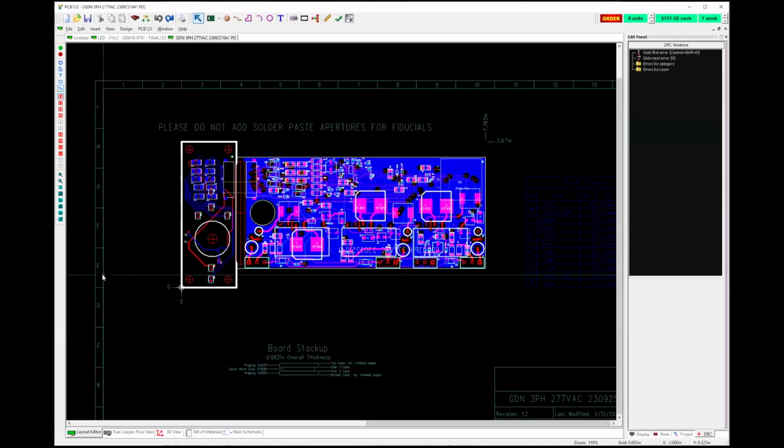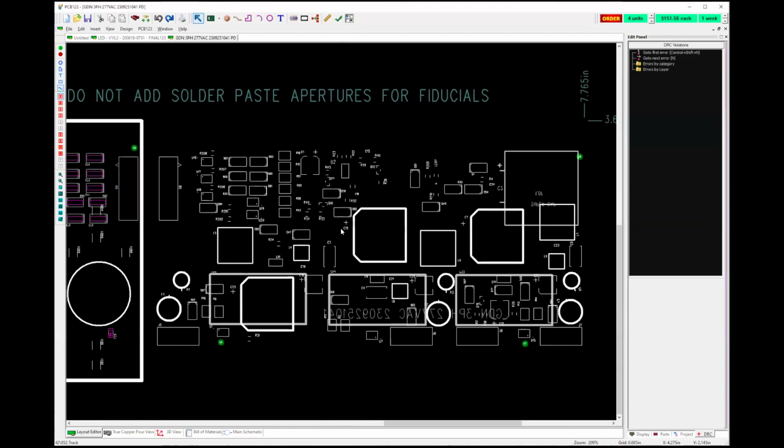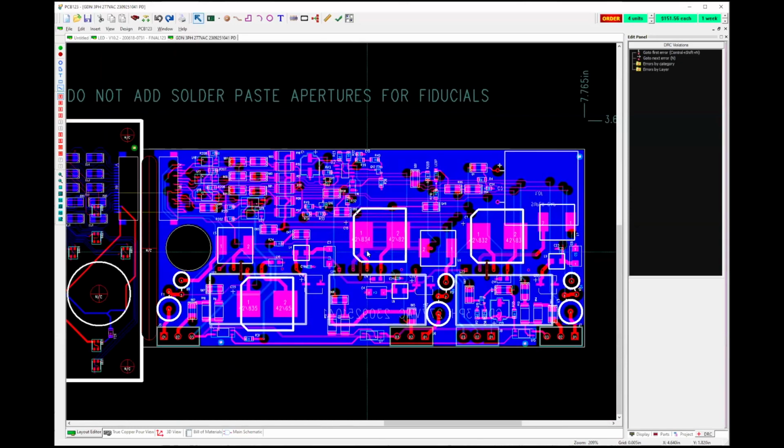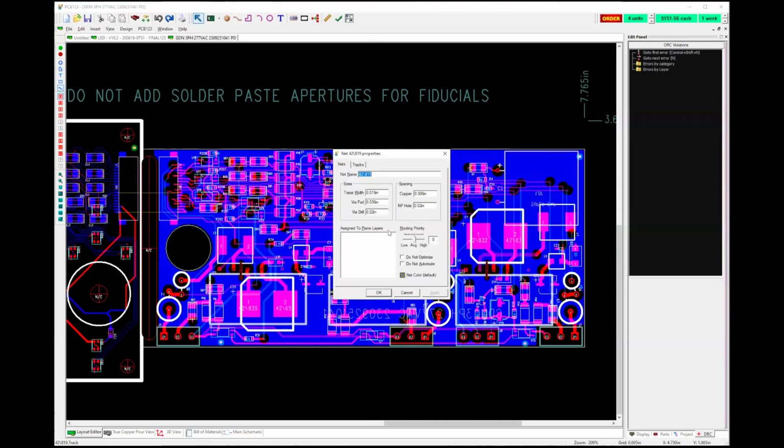Now, hey Bob, yes, quick question. Someone asked us if you could do differential pair routing. That's a manual thing. You can, and I've done quite a bit of that. So it's not hard, and you can check the length of wires to make sure that you're not too far off. You just highlight a wire like this, type P for properties, and it shows you the